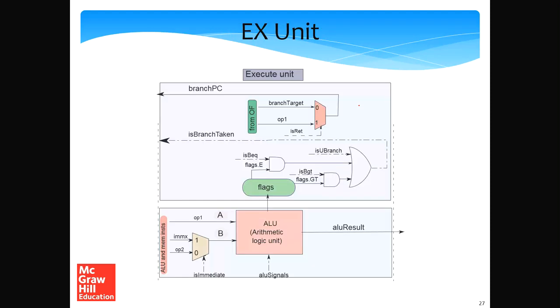Given that, we can use transmission gates for two purposes. One is to isolate the inputs of a specific subunit inside the ALU from the overall inputs of the ALU to save power. And second, we can build a large multiplexer with the help of transmission gates. It's doable. So let us summarize our discussion up till now.